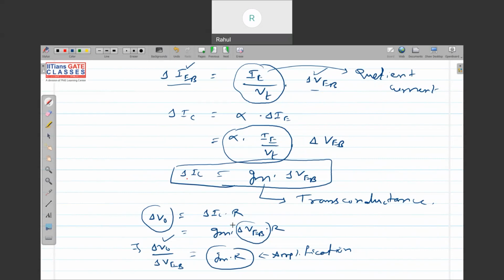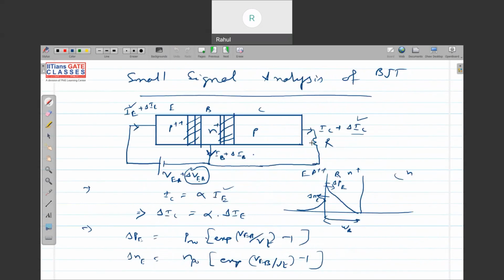So one more thing. Since the voltage here is positive, negative like this, this is nothing but V0 plus delta V0. So this may forward bias the transistor. When it is forward, P is positive, N is negative, then the collector base junction is forward, and the transistor action will not take place. For the transistor action to take place, the base to collector junction should be zero bias or reverse bias.